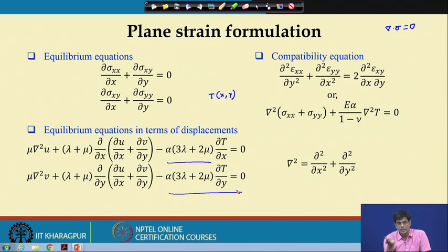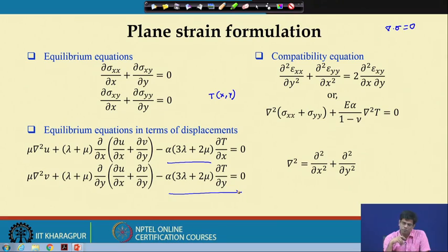So, in a thermoelastic case, even if you are following uncoupled thermoelasticity, even if you do not have an explicit body force, thermoelastic deformation will occur due to this change in temperature, that is T, since T is a variable here. Variable means it is spatially varying. So, that means it is not constant. So, these quantities will be non-zero. That means this will give you an additional body force.